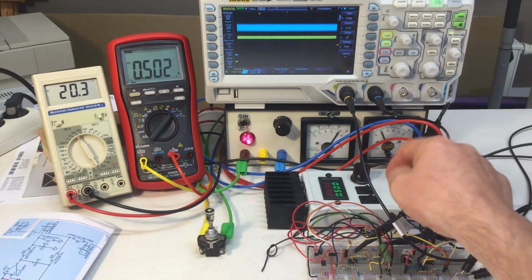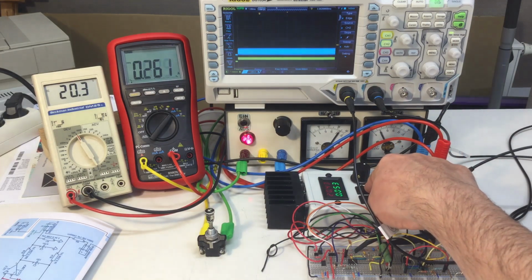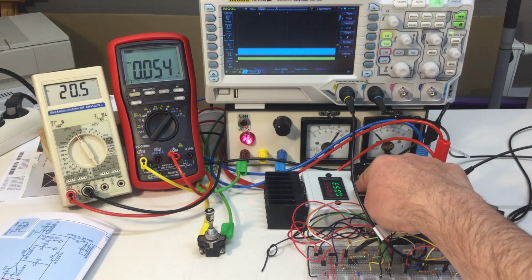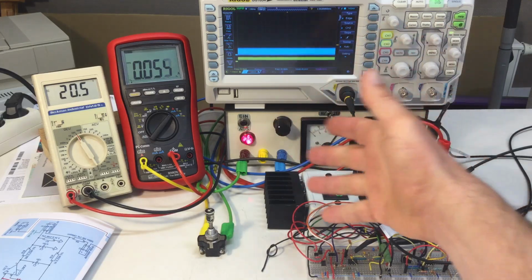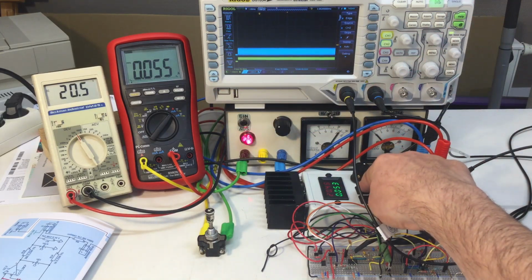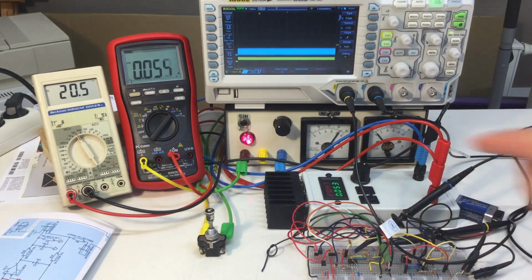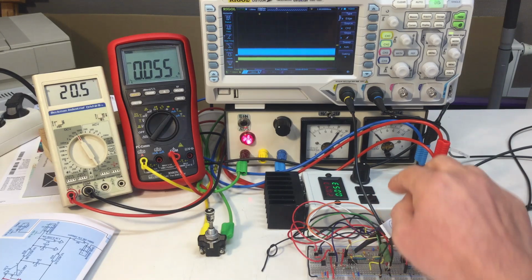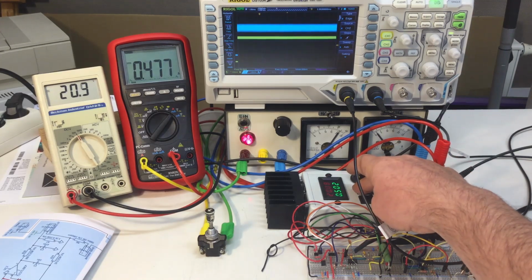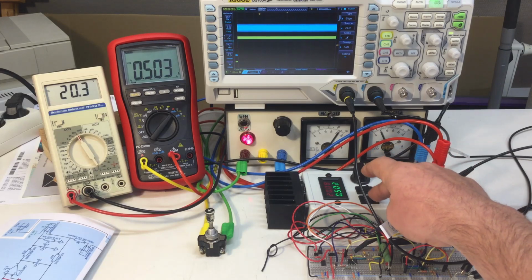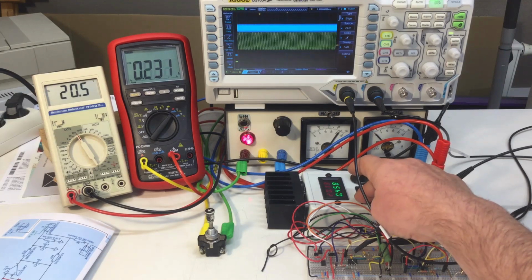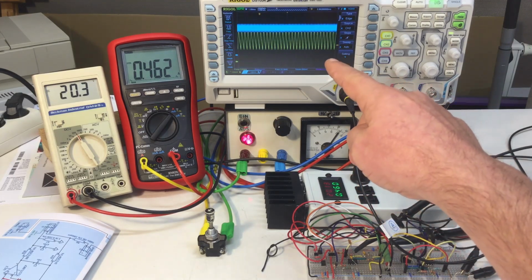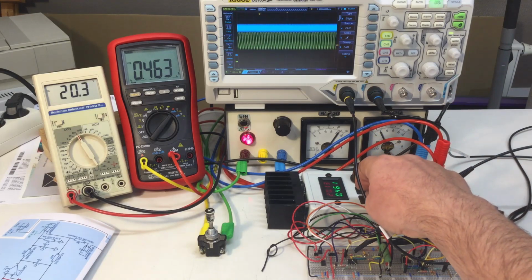Full view again, changing the range switch. 500 milliamps, 50 milliamps, or with my 5% resistors, 54, 55, whatever. Yeah, works like a charm. So let's go to the 500 milliamp range again, and now try switching it off. Okay, that's easy, but switching it on, there are the oscillations again.